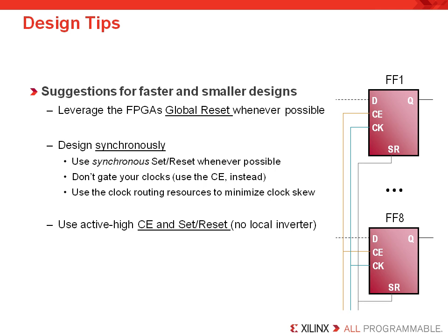And don't forget to keep your control signals active high so you don't need a local inverter to be mapped to each control signal input. These are not dedicated in silicon, and that could force the synthesis tool to waste LUT inputs.